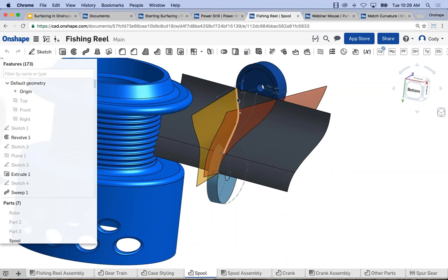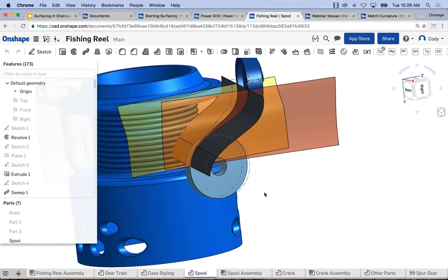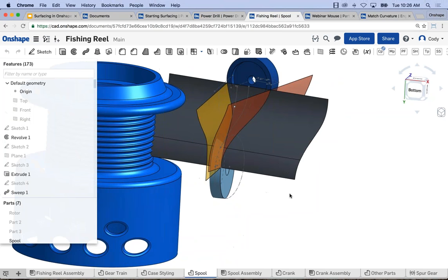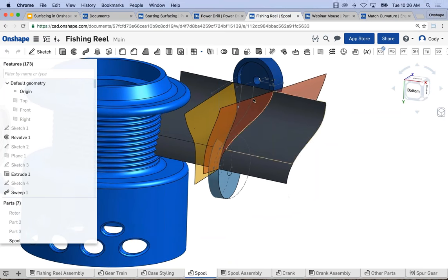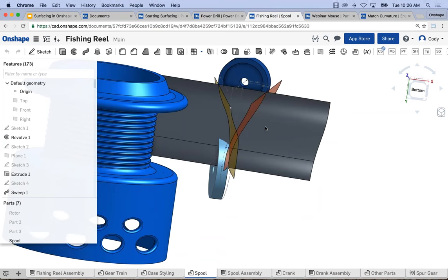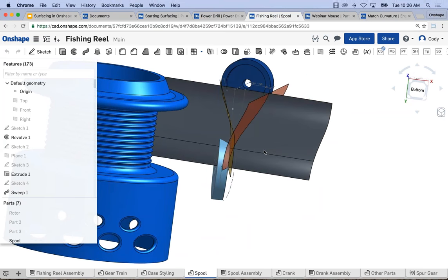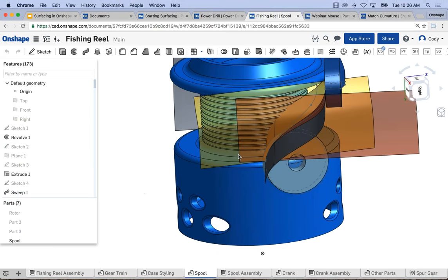I can click on an edge, for instance, and define that as the guide for my loft, or the profile, the path, for my sweep. So just creating these surfaces, extruding them, you'll notice they're just extruded to any depth. They're just there for construction, so the depth is not critical, but they're there just to help me figure out, okay, what's the relationship of this part to this one, and allow me to set the angle of that accordingly.